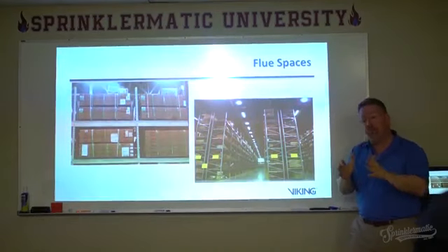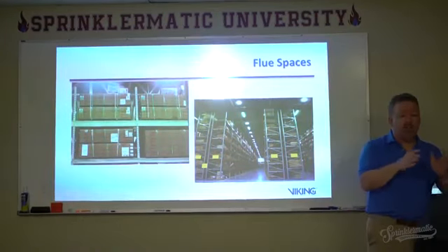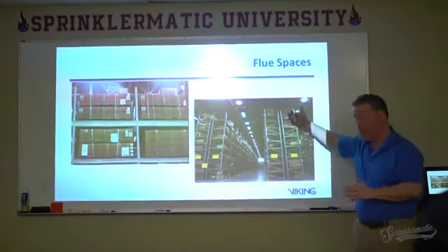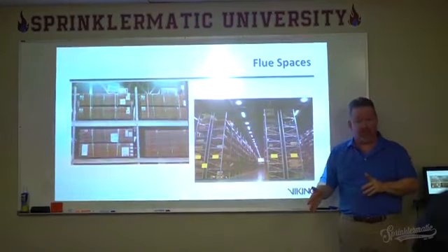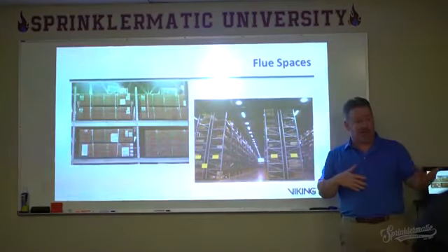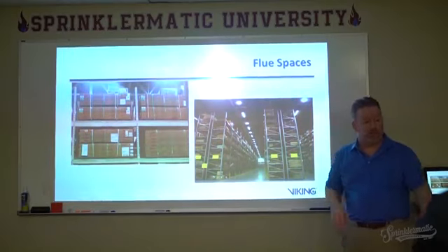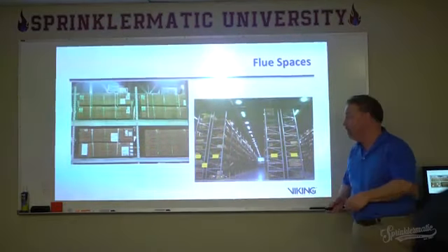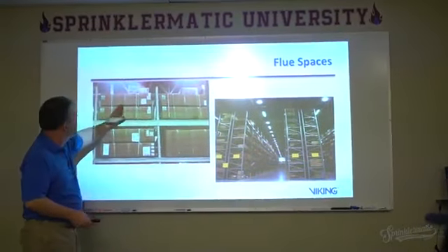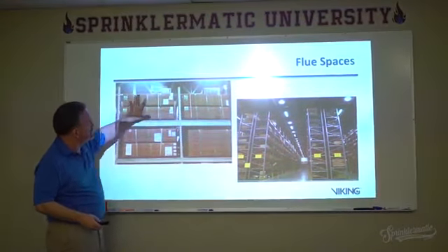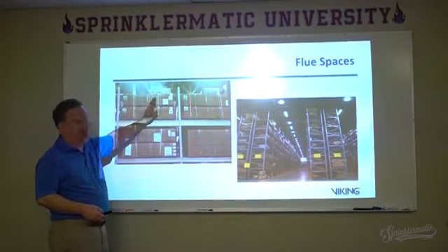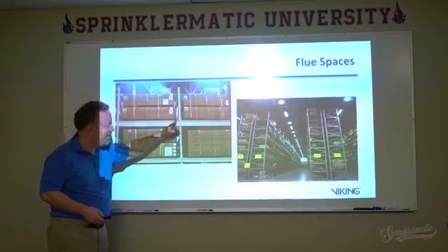Okay? So flue spaces become a critical component not only to the design, where the designer is assuming flue spaces are going to be maintained, but also to the inspection, to the inspector coming around, making sure that flue spaces are being maintained. Because remember also, let's just say I got a couple of smaller loads in here, but I can only put two loads in here because I need to maintain my flue space.